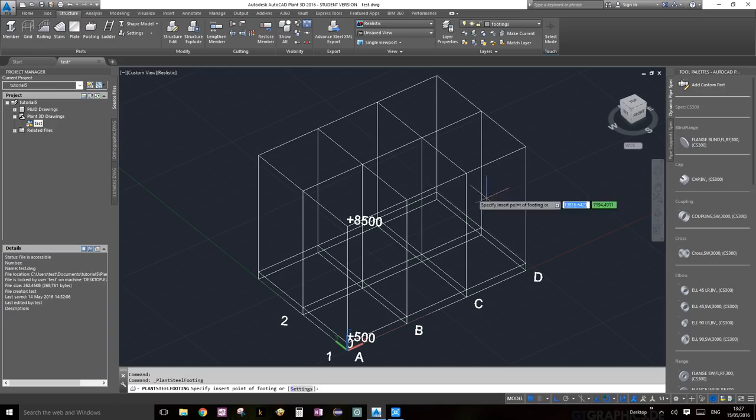So you're going to click on the footings, and once you click on it, as you can see, it's going to ask you to specify the insertion point, but we haven't defined what the footing or what the size of the footing is. Every time you make any kind of option, choice or command on AutoCAD, the command line at the bottom is always going to give you extra options. So always make a habit of reading it.